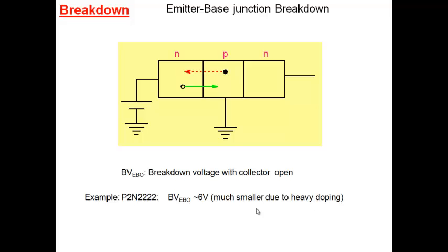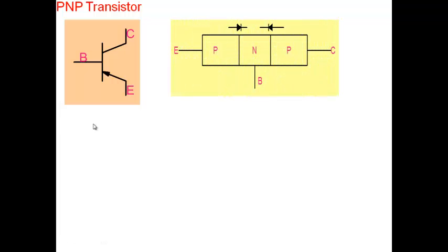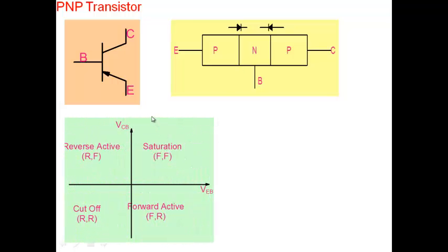All right. So far we've talked about NPN. PNP is similar. We have the PNP, and the distinction to keep in mind is that the directions of the diodes are reversed here. We have the same picture, except note the difference: the emitter-base junction is forward biased when you make VEB positive. When you make the emitter more positive compared to the base, you're forward biasing the base-emitter junction, which means that VEB has to be positive.